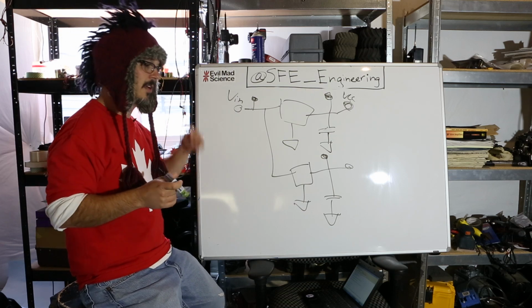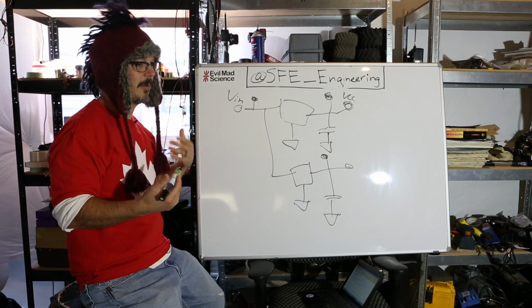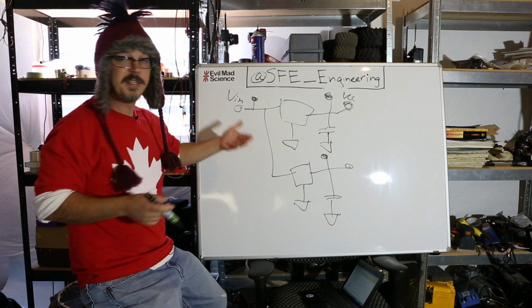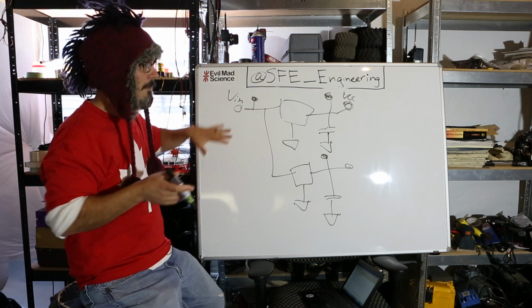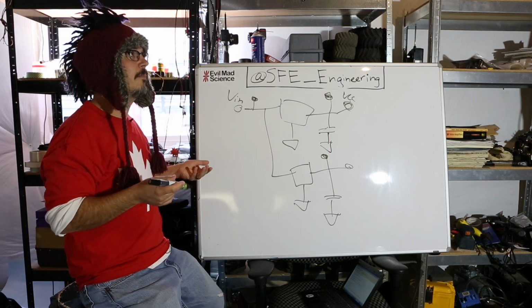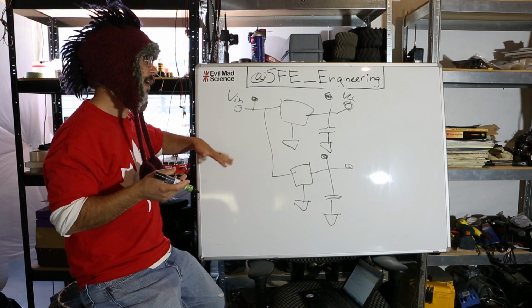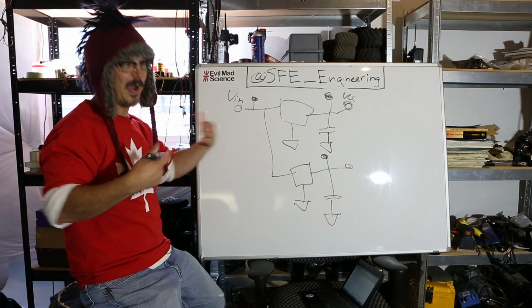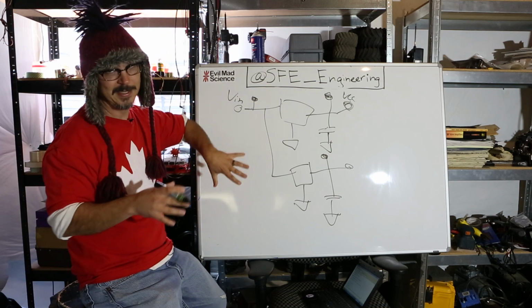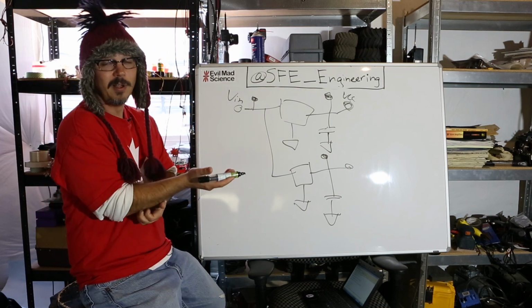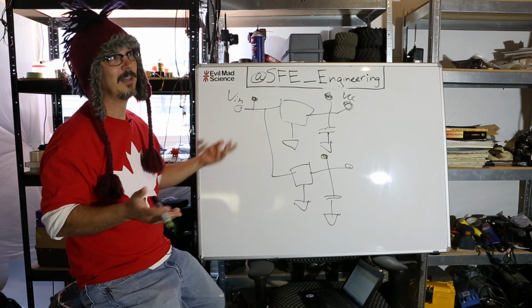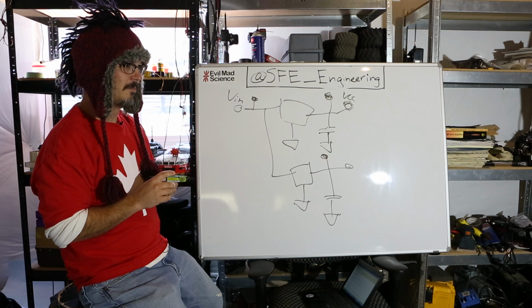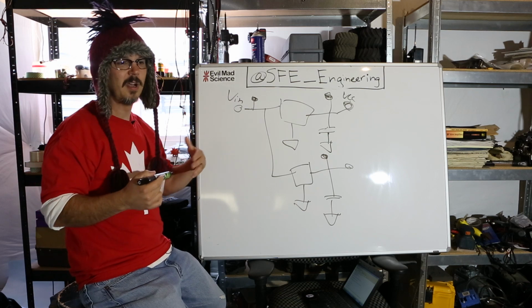So if you're designing a predominantly digital circuit, you may want to read something like a reset pin on a micro, or various other pieces, or you may want to keep an eye on when a certain digital part is coming up, right? When it's powering up and when it's active, so there might be a couple of pins on that. If you're designing an analog circuit, and I love op amps and I love my transistors, you're going to want to know about specific voltages according to that.